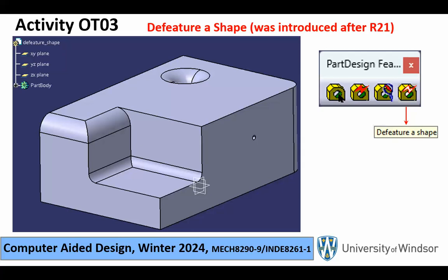So what you want to do is go there and, for example, make sure that all the fillets in a certain range of radii disappear. They don't participate in the solid model. Or you want to make sure that any holes in a certain range don't participate. So defeature them from the dumb solid model that was sent to you. You don't want to go ahead and find them and then delete them, you just want to defeature them. So I'll do an example for you of this type.